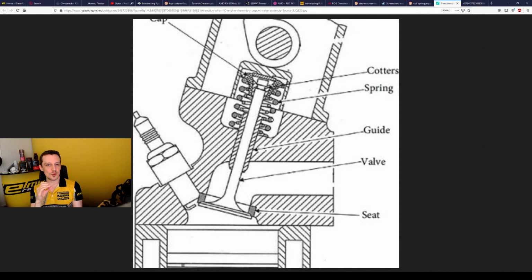If you ran a tube type spring instead, you could reduce the mass a lot and have a much higher force per mass ratio in the spring than with these solid springs. But I'm assuming this is a manufacturing technique problem, why these aren't tubes.